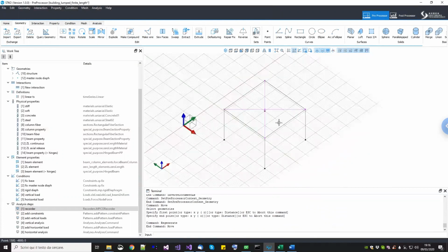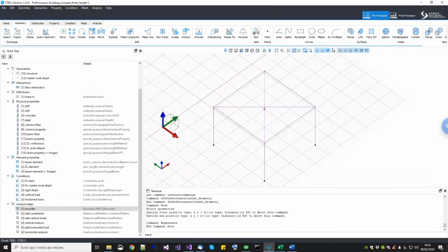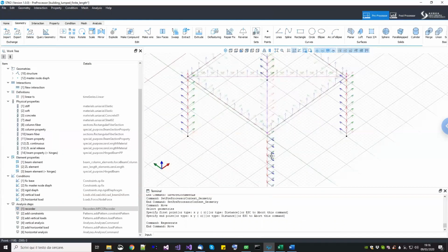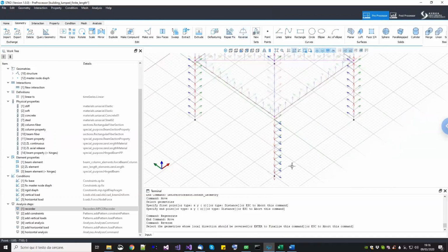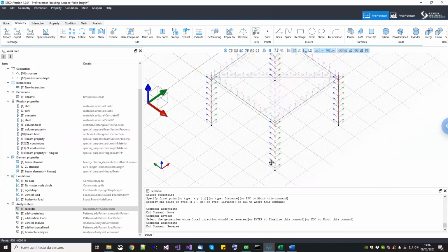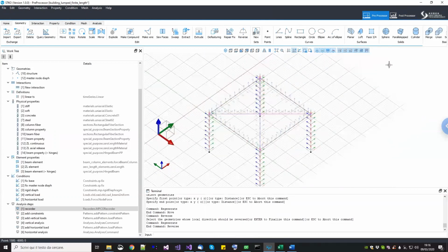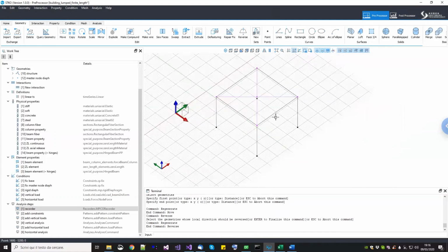Now let's check that after this modification, the local axis didn't change. In this case, as you can see, this column is pointing downward. As you know, it's easy to fix, even though it is not mandatory. Okay, so it is pointing upward now. This is fine. Now we do the same modification we did before to convert this distributed model into a lumped one with finite length.